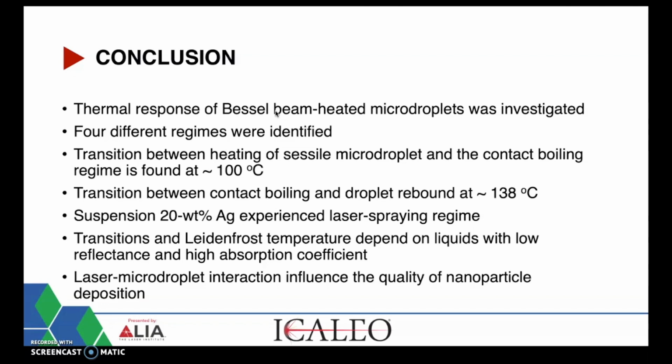The transition between the first regime and the contact boiling is found to be at a surface temperature of approximately 100 Celsius. On the other hand, the transition between contact boiling and droplet rebound, and perhaps the most important one, occurs at approximately 138 Celsius.